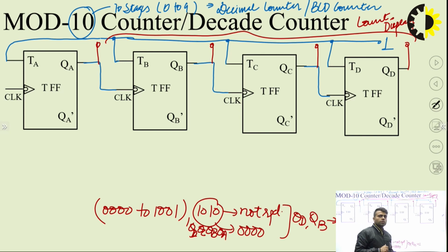So how is this going to happen? Because the output cannot control the flip-flop's behavior, we have to make some extra arrangement. For that, we will be using the additional asynchronous inputs available with the flip-flop, which are preset and clear. Preset is used to make the flip-flop's output permanently high, and clear is used to make the output permanently low. As long as preset and clear are activated, these outputs remain permanent, and if you disable them, then normal flip-flop operation can be performed.